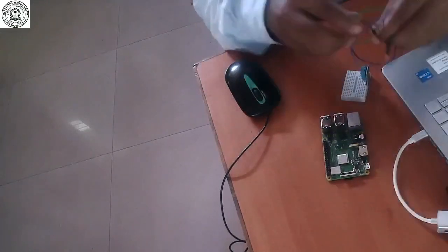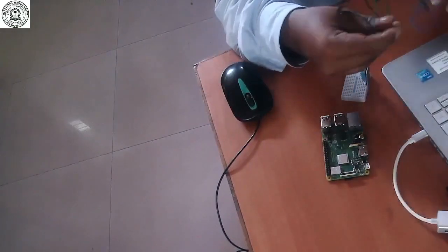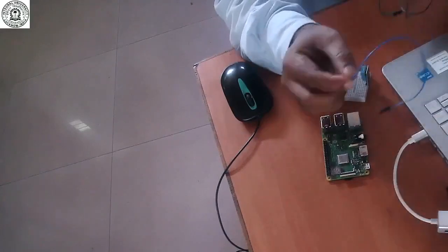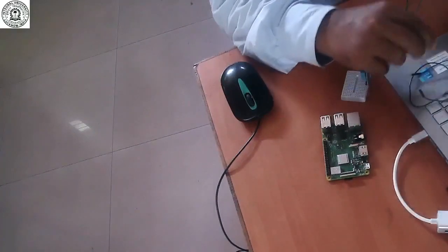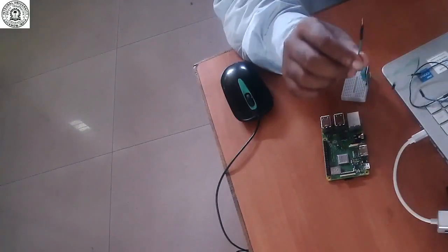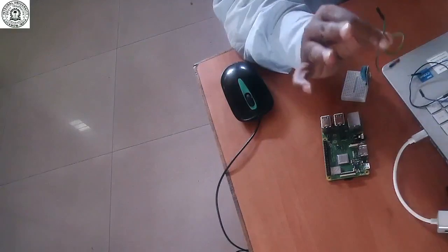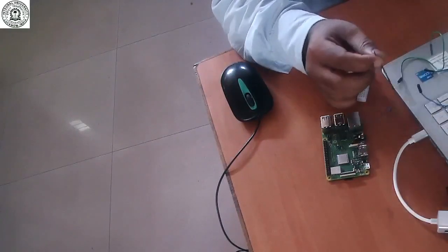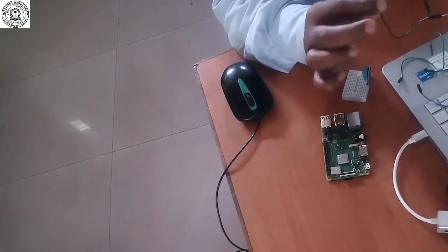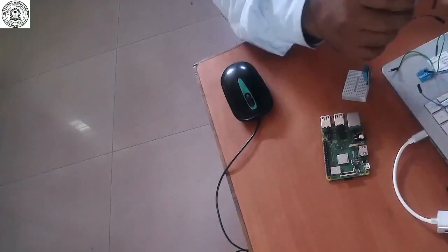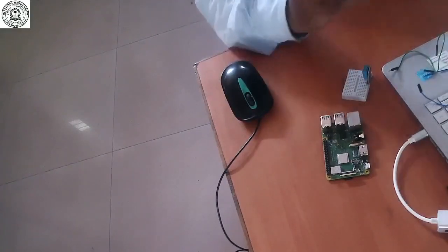So here I am using these three wires. I will use this blue one for the VCC connection, this black one for the ground connection, and this green for the data line or the GPIO pin connection. You can use any type of wire, but for remembering I will always try to use the black color for the ground one. No problem, you can use any wire for any connection. Obviously these are the male to female wires that I have already used earlier.